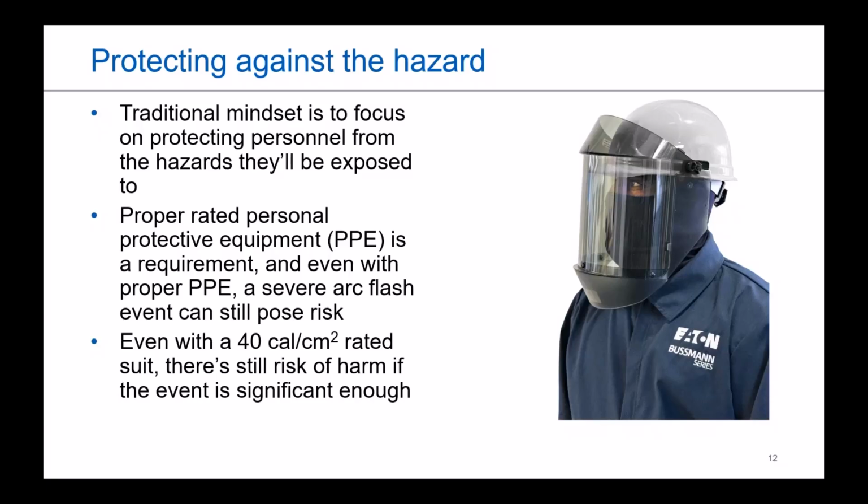One thing that leads into a lot of what we're talking about today is that even if you're wearing a 40 cal suit, the full space suit, there's still some risk of harm if the event is significant enough, because with that 40 calories per centimeter squared, we're really just talking about heat exposure. That's making sure your body doesn't get burned. But if you go back to that slide I presented with all the things that can happen during an arc flash event, there are still other hazards that PPE really isn't going to protect you from.